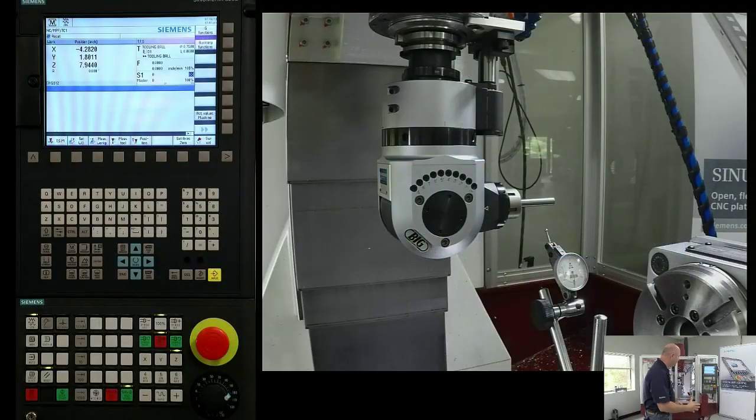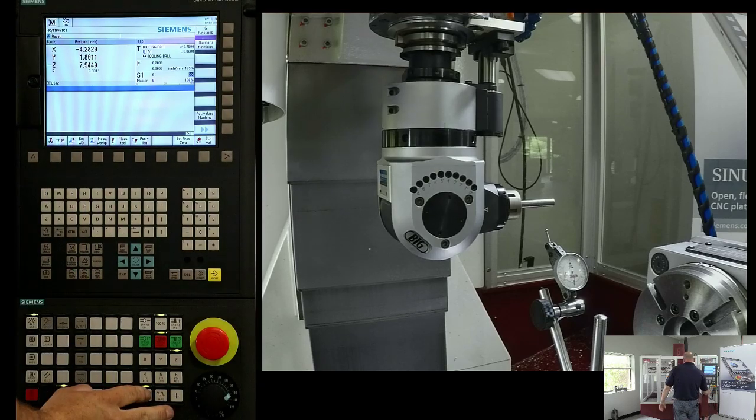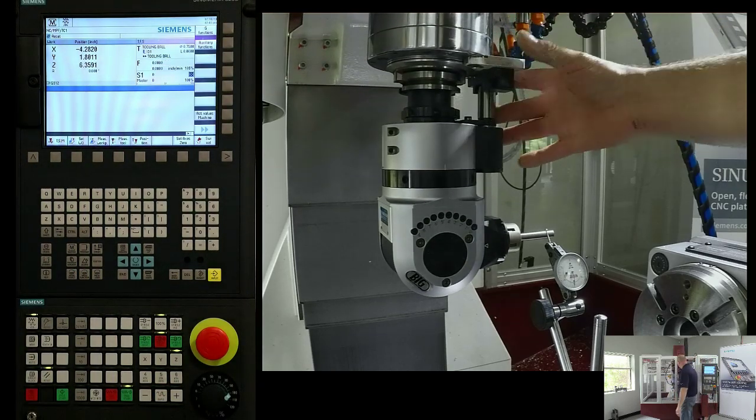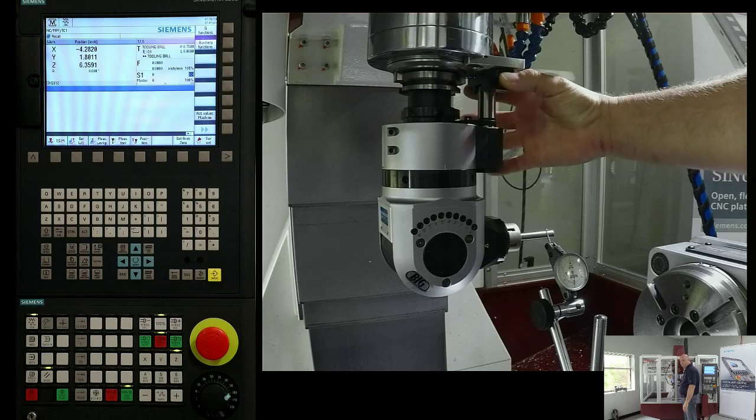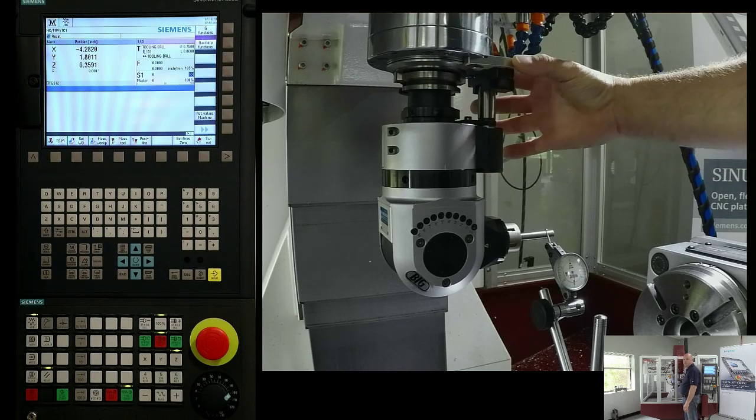Now, there's a lot of other stuff I'm going to need to know. So I'm going to have to go in and really go through and measure some mechanicals now on the machine to figure out where this rotary head is in space. Now, before I did anything else, I did create a mount here. I'm going to jog down a little bit. So you will have to do some mechanicals on these heads. They give you a little datum block, but the block does have to be mounted to the physical machine.